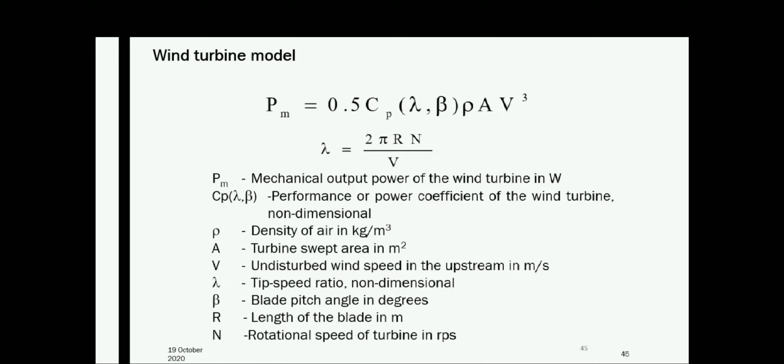So these variations lead to a dynamic perturbation in the output power, and hence a flicker in the generated voltage will be present in the power output generated from the wind energy conversion systems. In a constant speed wind turbine, power variation and voltage flicker do pose a problem in the network. But on the contrary, variable speed wind turbine systems provide a much smoother output voltage, and a more stable bus voltage with lower losses is achieved.